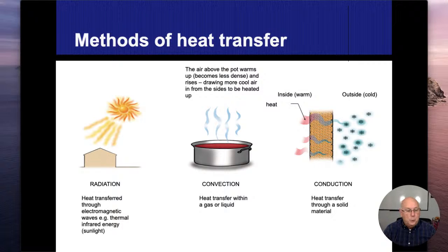Convection, anytime we move heat through water or air, we're going to be calling it convection. So in furnaces, we have ductwork. We heat up the heat exchanger. We blow our circulation air around the heat exchanger. We absorb that heat. The fan blows it through the ductwork into the rooms where we want that heat. That's moved through convection. Hydronic heating systems, we use water. So we heat up the water. We pump the water to another radiator, another location. We move the heat from point A to point B through water, hence convection.